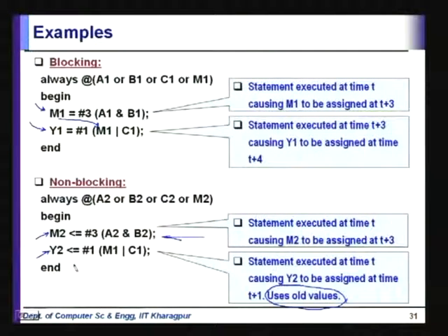So, that brings us to a very interesting point: what is the sequence in which the simulator is going to do this? What is the scheduling semantics of Verilog? Think of a set of modules, some having these always blocks, some being structural, etc. Now, at every point of time, we have certain events which are active. In other words, those events can be executed now because there is nothing that blocks us from executing them.